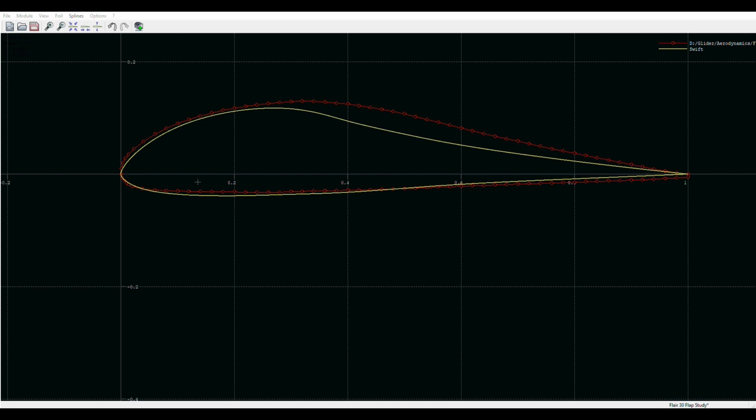Front end, highly similar. Flair's got a rounder leading edge that can help soften the stall characteristics sometimes. And its maximum thickness point is further aft. They trip the flow later on. The Swift trips the flow up here about 30%. And they both are using some form of Stratford pressure recovery technique. And that's to generate high lift at relatively low drag. And when you do that, you get these interesting shapes aft of the maximum thickness point where you're recovering the pressure as fast as possible without tripping it into separation.